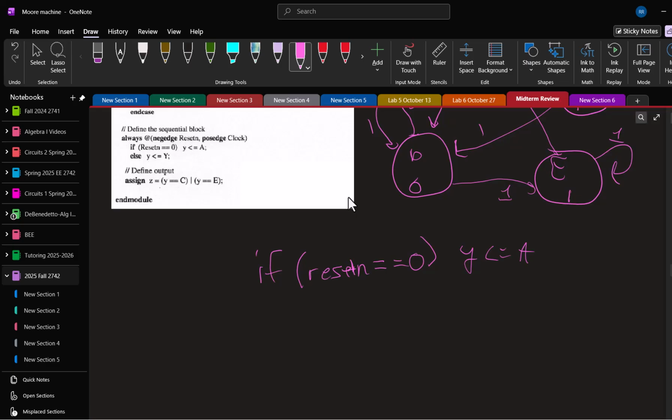So when this variable is 0, that means reset. That's why it's called reset in, because usually if I had reset, we would probably have if reset equals 1. So the in is just saying it does what it does when it's at the low value. Okay.